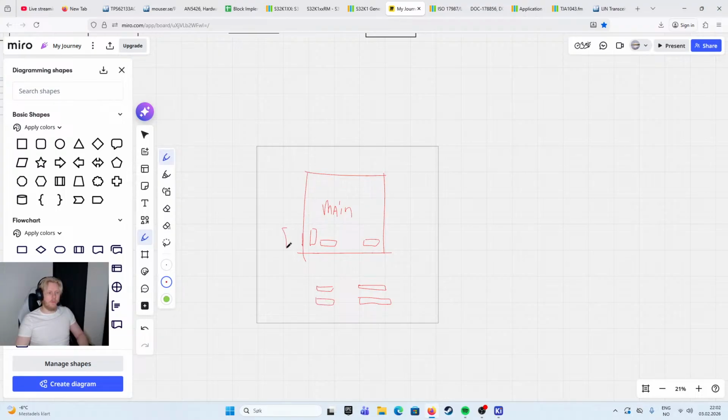And then cables over. So in this case, it would be three wires: power, ground, and LIN, for example, if we are the ones powering, which we should, I guess. Same here. And then we can measure and put some test points on all of these PCBs. It won't be this big, probably. It'd be a miniature. I like small ones.